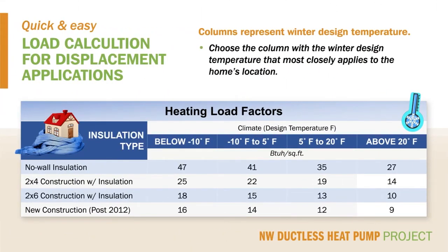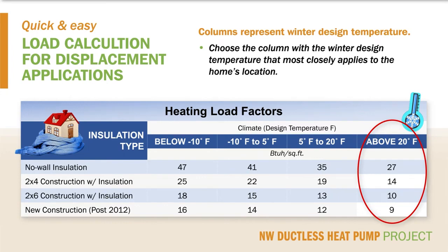The first step in applying the quick and easy load calculation method is to identify the column that applies to the home. The column represents the winter design temperature for the location of the home. If you do not know the winter design temperature, ask around or search online.